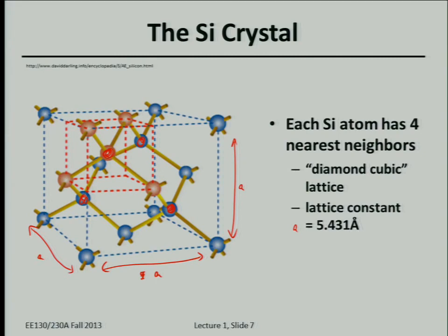So it turns out that these interior atoms, if you draw a cube diagonal, from this corner all the way down to this corner, oops, maybe I didn't draw it right. Oh, okay, wrong diagonal. You draw a diagonal from this corner down to this corner, you'll see that you have an atom 1/4 of the way down. Oh, and I did draw it correctly here. So here's another diagonal here. There's an atom 1/4 of the way up. Okay, so there are 4 cube diagonals, and the interior atoms are 1/4 of the way along the cube diagonals.